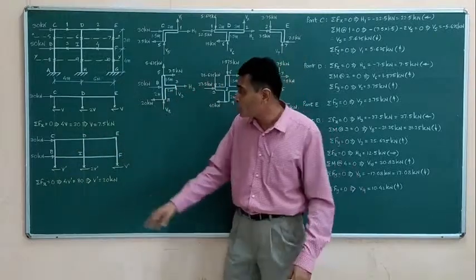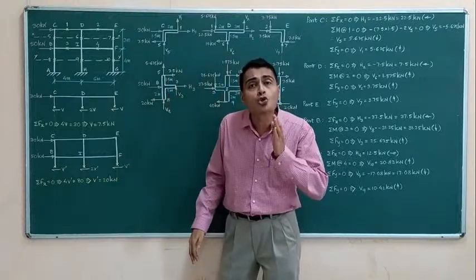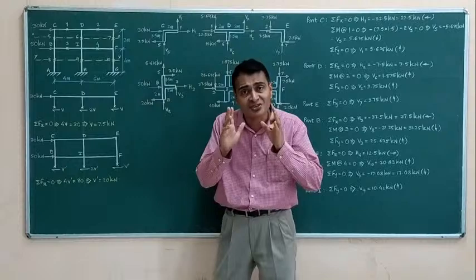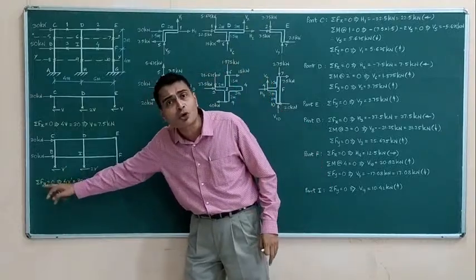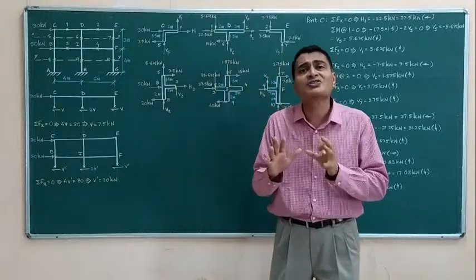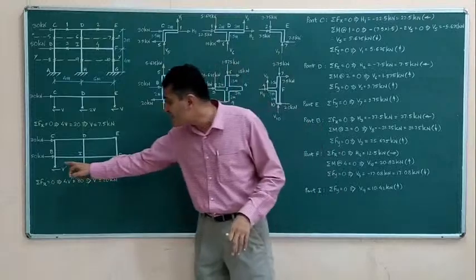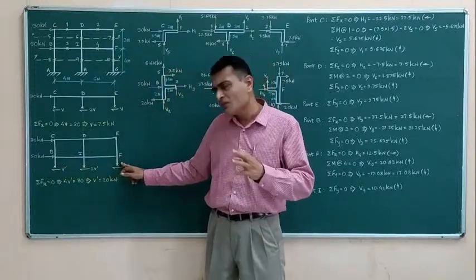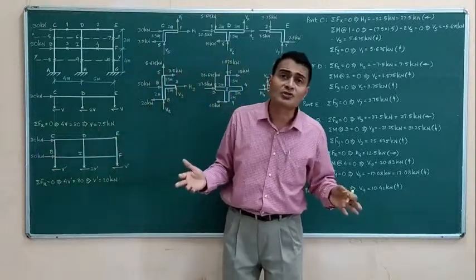So the FBD is showing shear force at these columns. FBD is not showing actual forces in these columns, but actually they are existing, mind you. But since I again use sigma Fx equal to 0, I am avoiding showing those unnecessary forces. There will not be any moments at these points because these are points of contraflexure. And of course FBD is showing 30 kilonewtons and 50 kilonewtons.